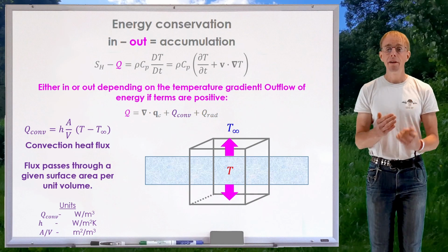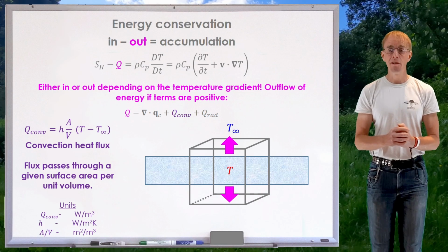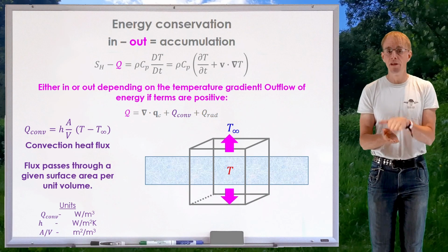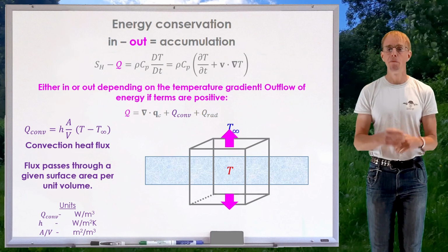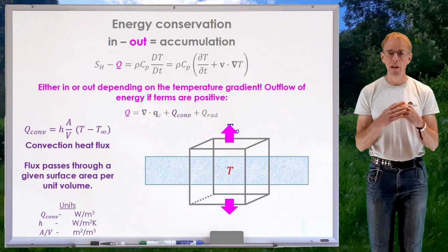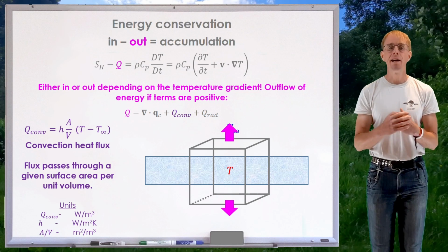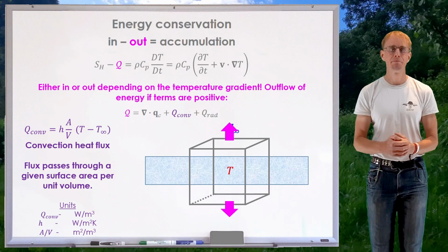And so that energy crossing a surface is due to natural convection. And I can see that if my polymer is hotter than the external surroundings, then I have heat transfer away from that polymer across the faces of my little control volume. And so again, that is a positive heat transfer, and that reflects a heat loss. It can, of course, be the other way around.